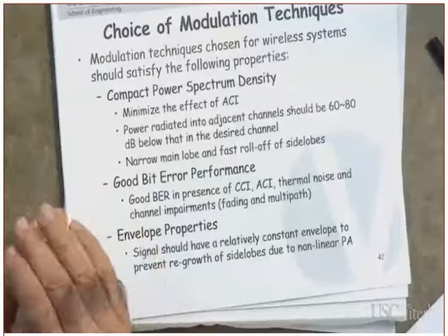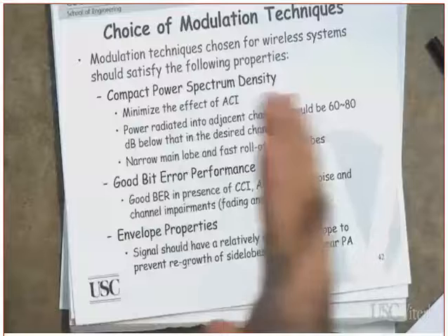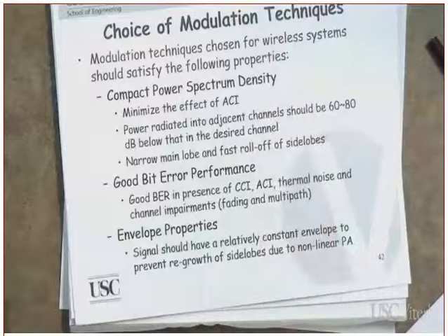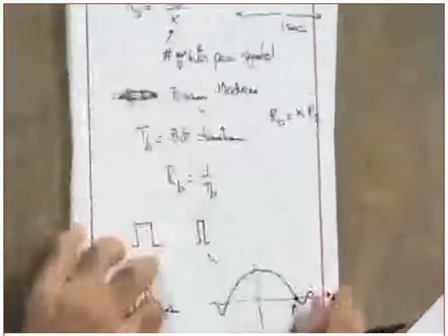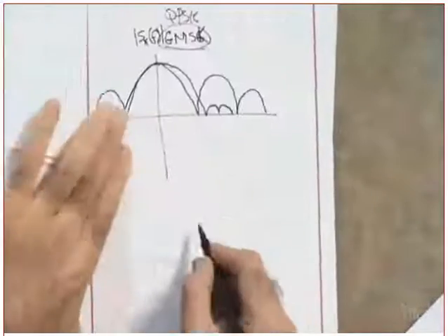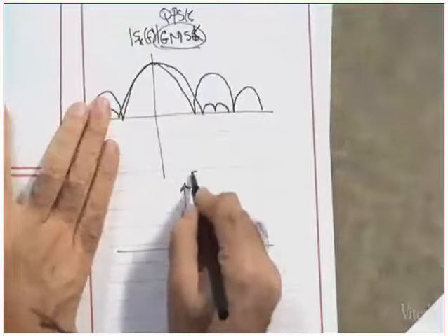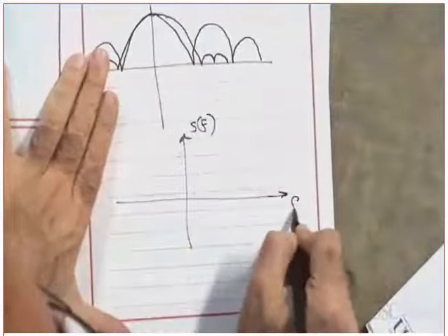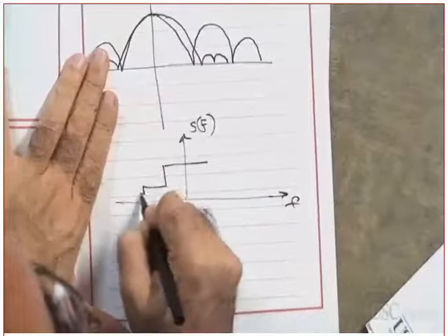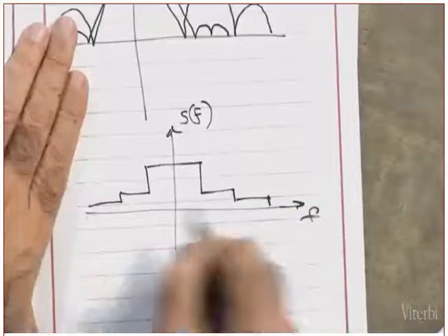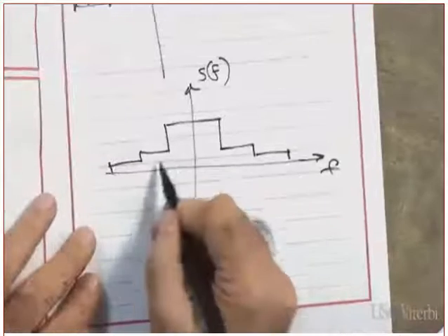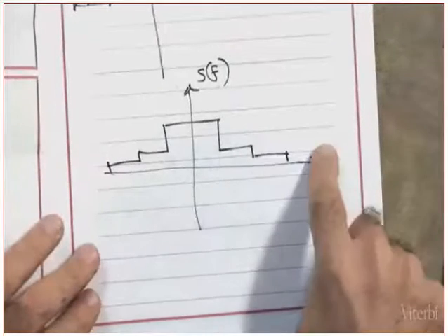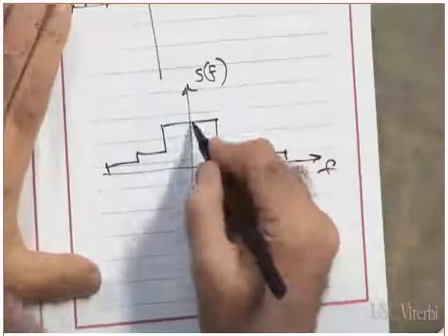Now the FCC, by the way, whenever they come with a standard, they will define what is known as the emission spectrum boundary. Are you following the boundary? When they sketch the boundary, everything is like this. This is the spectrum. It tells you your emission needs to be bounded within this. In other words, your spectral density needs to be like this.